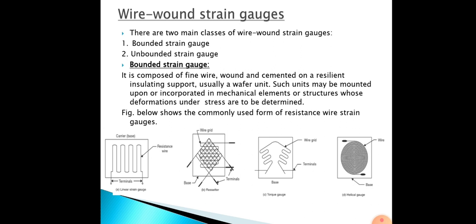In the unbonded strain gauge, you can see in the diagram that M and N are attached by rods. M and N are the two points between which displacement is to be measured. The pickup and measuring networks are energized from a similar isolated source. Unbalance originating in the pickup is detected, and a servo-actuated balance of the measuring network provides a reading of strain on a graduated scale.